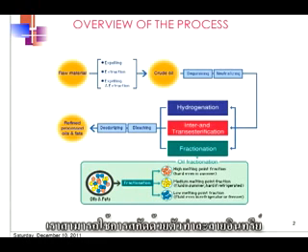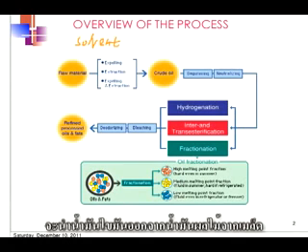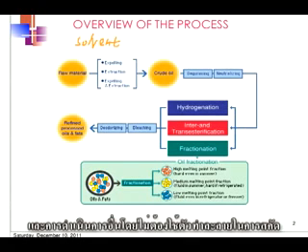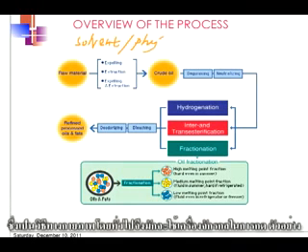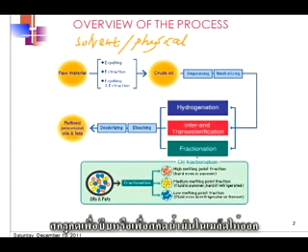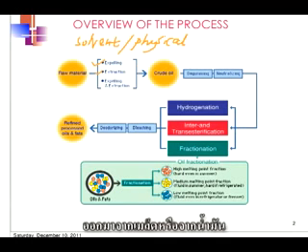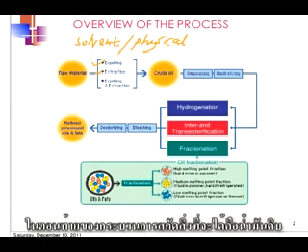We can use an organic solvent. So this is a solvent extraction, which will extract the fat or the oil from the fruits or from the seed. And another process is without using solvent, which is basically we call physical extraction. Usually this is using a mechanical press, for example a screw press, to expel or to extract the oil physically out from the seed or from the oil. At the end of the extraction process, what we'll get is the crude oil.